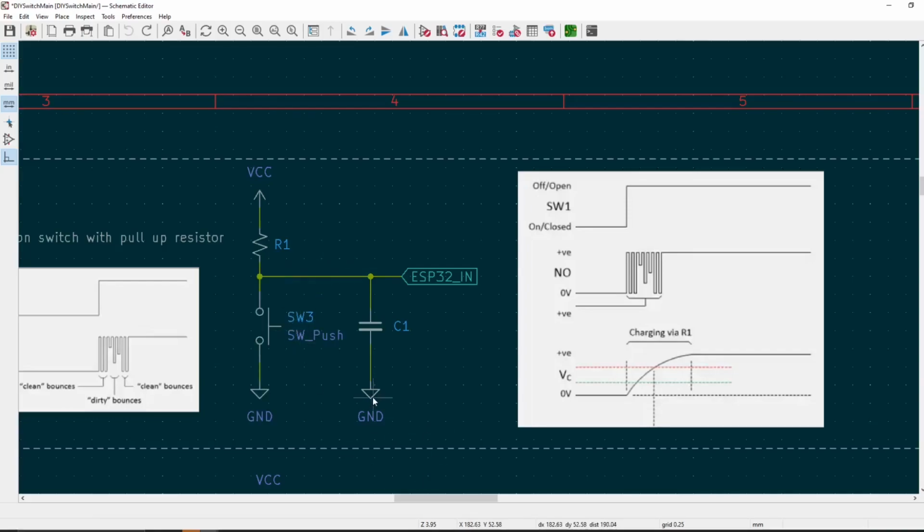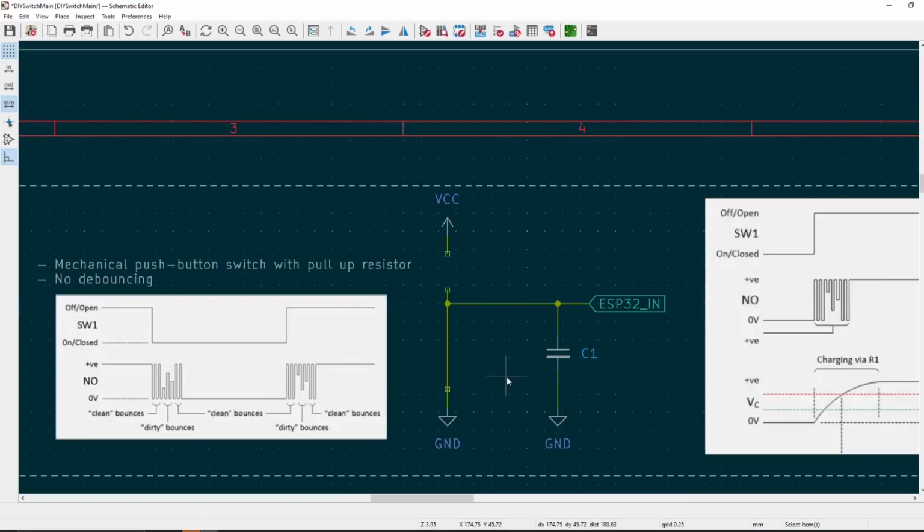But the problem with this approach is now, for example, if you can imagine that we would now like to discharge our C1, or in other words, just press our switch. When our switch is pressed, that's what I represent with this now, we will have a circuit like this. So basically it means that we would discharge C1 to the ground via this short circuit. This is exactly not a short circuit. We have some resistance here from a closed switch itself, but it's very small.